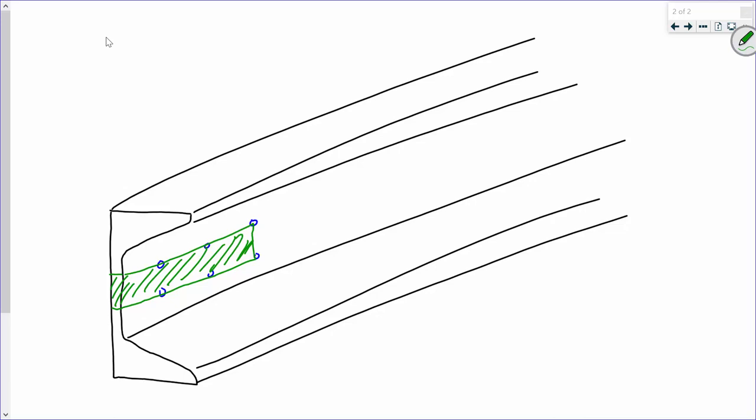It would be 1. And the reason why is because if you look, there's all these cases in the shear lag table, in table D3.1, right? But all those cases below are special circumstances. Really, the 2 cases that matter are case 1 or case 2. And case 1 says if every component of the cross-section is connected, U is 1. If only some of the components of the cross-section are connected, then you use 1 minus X bar over L. Okay?